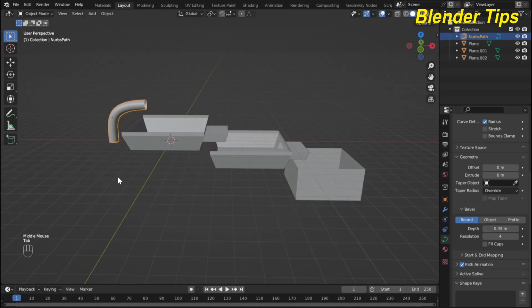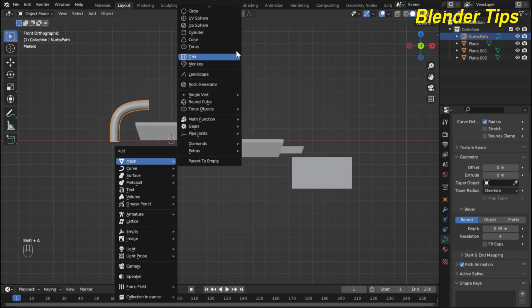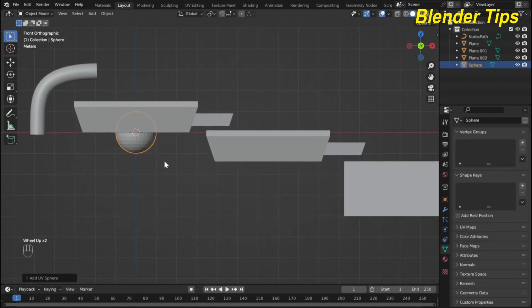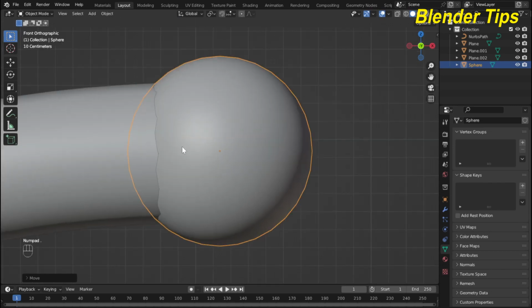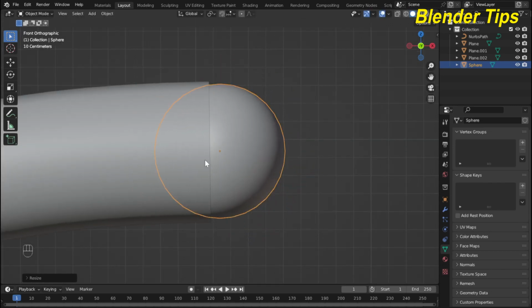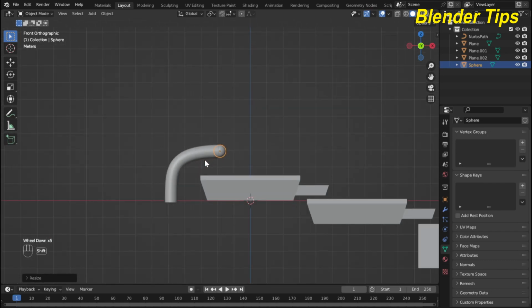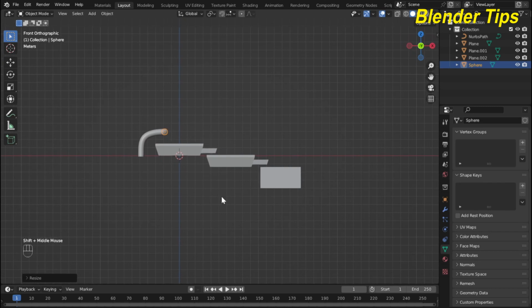Back to the object mode and now I want to add a blue object, for which I add a UV sphere and also make it shade smooth and scale down this and move this and also press numpad slash to focus this and also scale down to adjust this. Nice. Beautiful. Now I want to add a domain for all these objects.